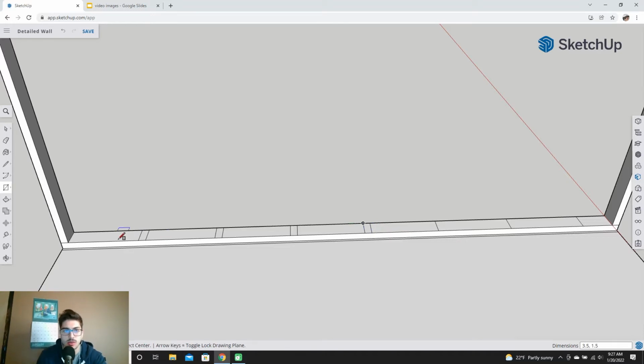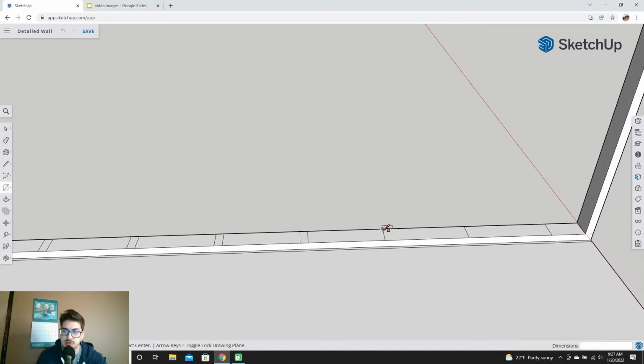Like you could say, oh, well, if I would cut all of the spacing down to 14 inches, I would get an even 14-inch gap here too. That's kind of incorrect because you want your studs to be spaced at a standard sizing. I probably will have some DIYer in my comments like, I do even spacing all the time. I don't care.